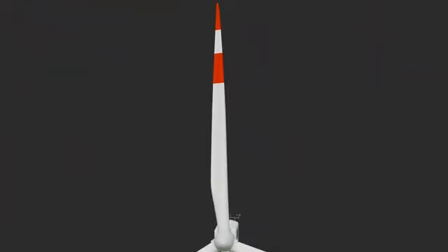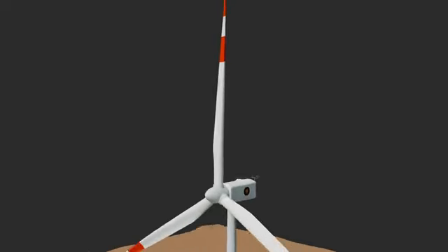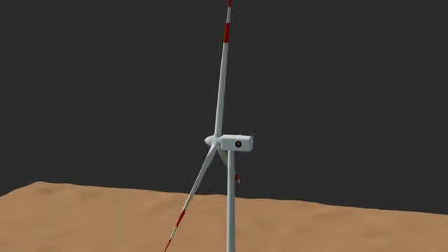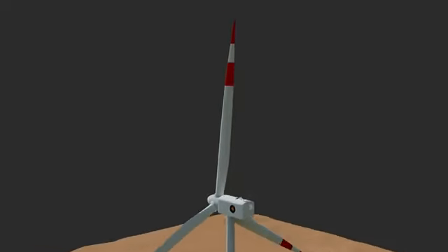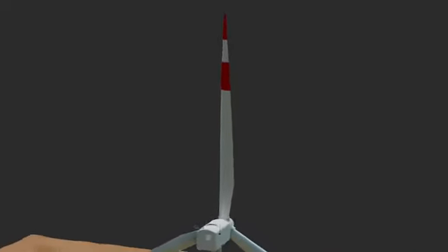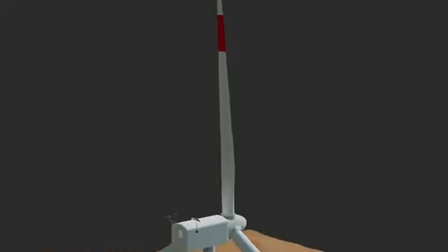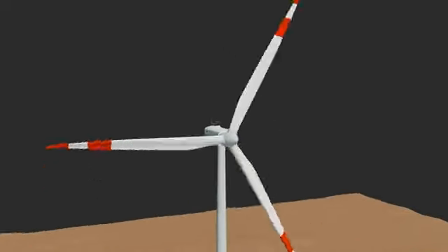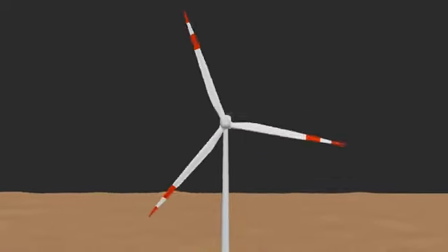The blade functions as a massive cantilever beam. Internal bending stress is maximum at the fixed root and gradually decreases along its length, becoming zero at the free tip. To withstand this maximum bending moment, the blade requires its largest and strongest cross-section at the root. Tapering also serves critical aerodynamic functions.